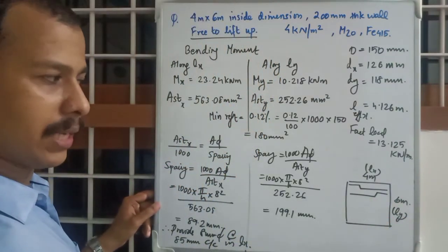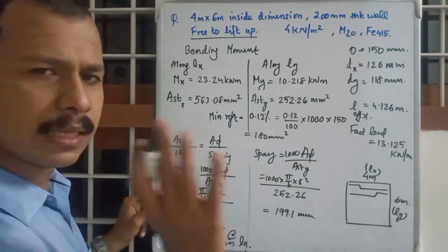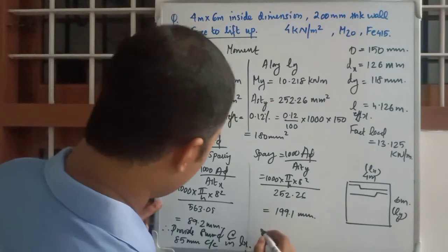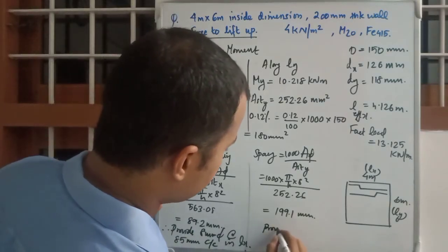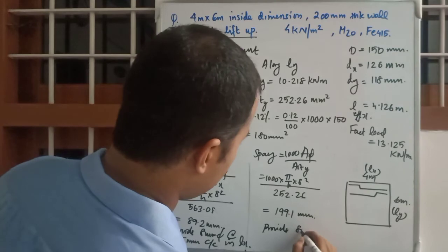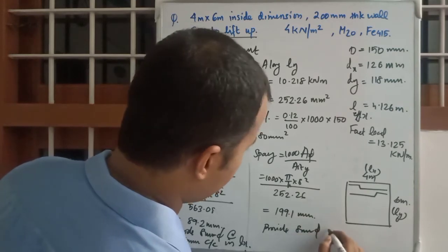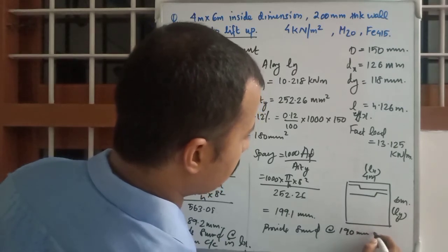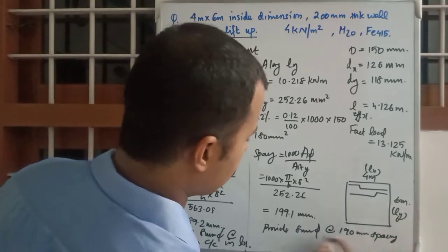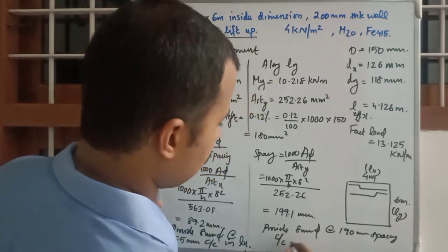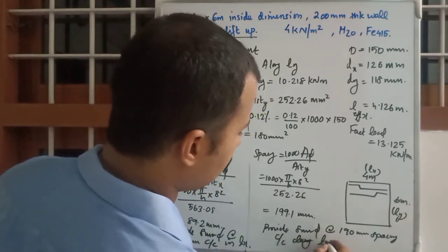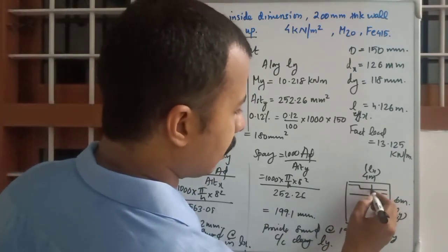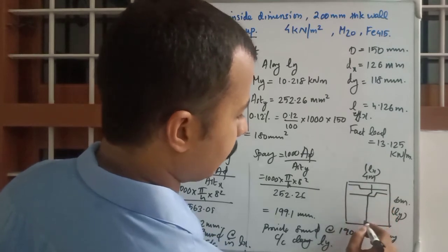Okay, cranking in both directions with the dimensions in the one-way slab itself. Okay, Lx. In here, what will be? Provide 8 mm dia bars at 190 mm spacing center to center along Ly or longer dimension. In here also we will be having cranking.